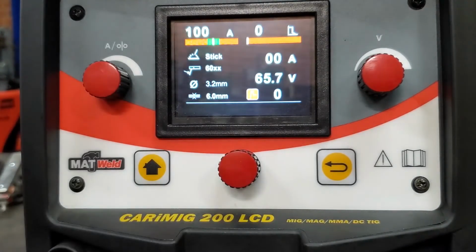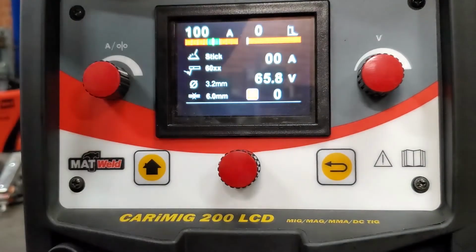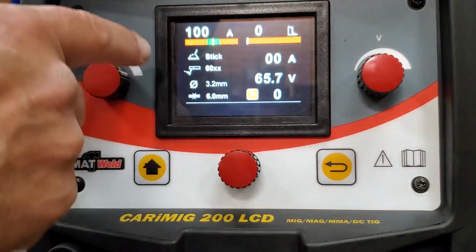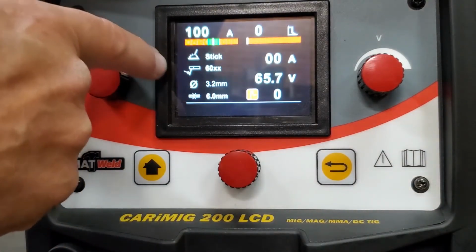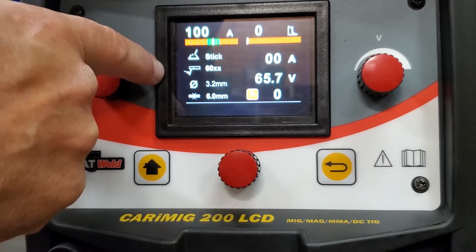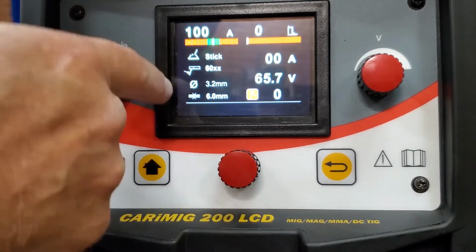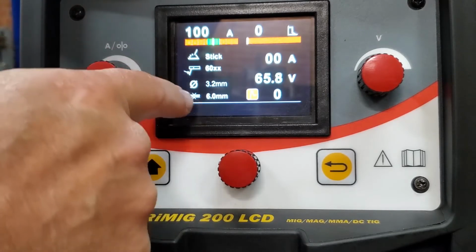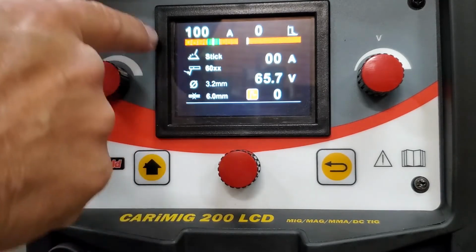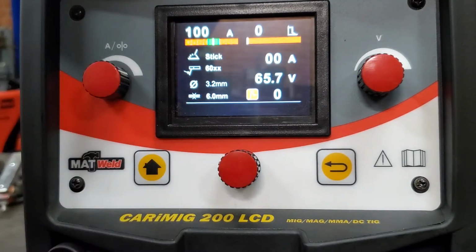Enter. On this screen, a summary page, you will see you've chosen stick welding. You've got a general purpose 60 code, a 3.2 rod and a 6 millimeter plate. That gives you 100 amps. If you are not happy with